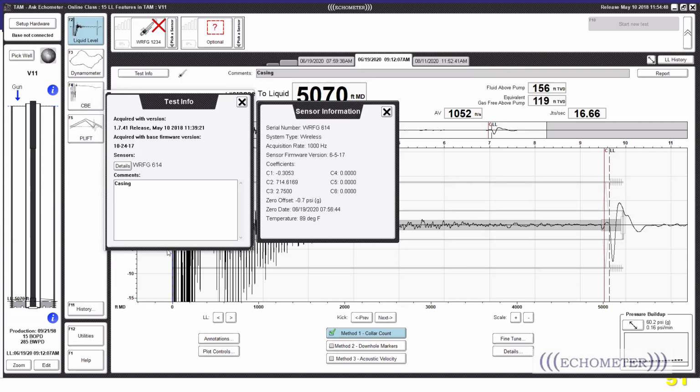So you mentioned in the comment, Melina, if you have a zero offset of 1 or 2 or 0.1, that's fine. That's what you want to see, until you start seeing a really big drift. That's kind of what you're looking for. But as far as how it can be solved, if you have a really high offset, then you might want to send your transducer or your gun, if you're using wireless equipment, in for us to possibly recalibrate. That's a good point. You can track just by looking at your previous offsets. You may see when the pressure transducer may be out of calibration.